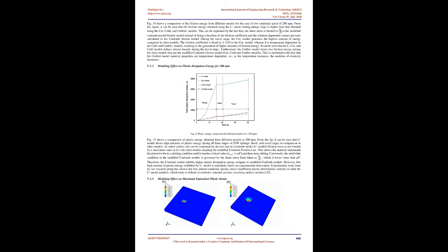This can be explained by the fact that the friction coefficient used in these models is constant, i.e., not temperature dependent. This deviation in temperature profiles continues after the experimental temperature profile reaches its peak temperature. Results from the CMFT and CMFTWT models are closer to the experimental result. This is more true for the CMFTWT model, which produces the results that are closest to the experimental temperature profile throughout the entire weld process. This can be attributed to the fact that the CMFTWT model takes into account the temperature-dependent thermal properties of the workpiece in the model.